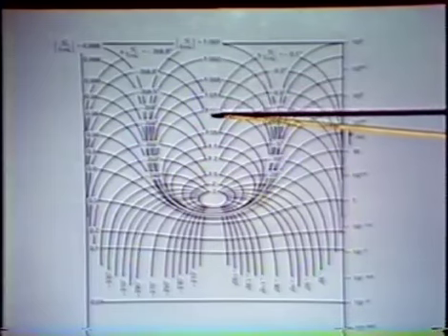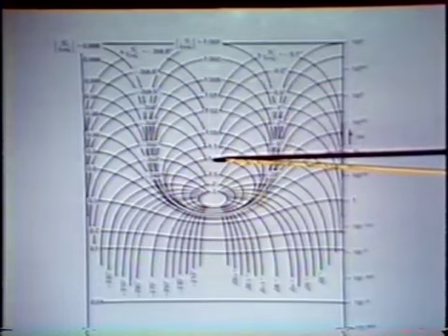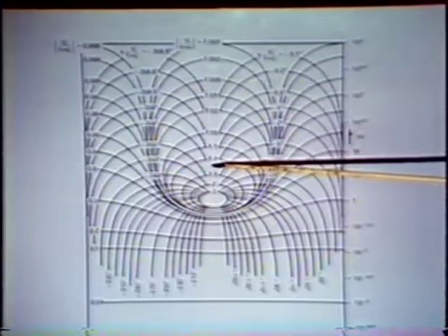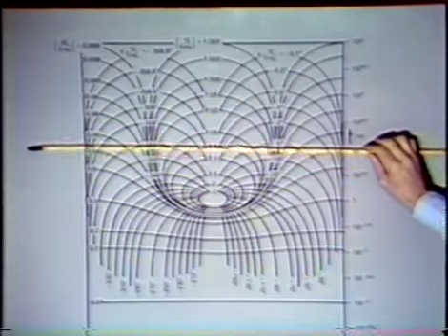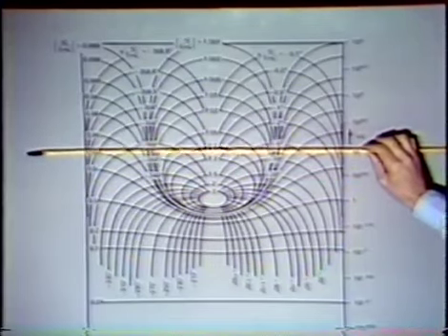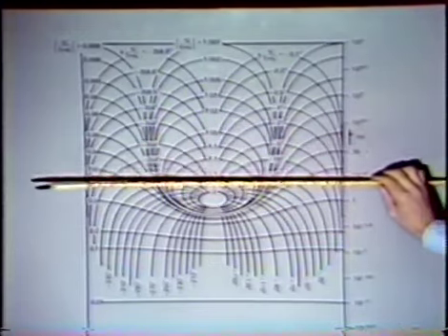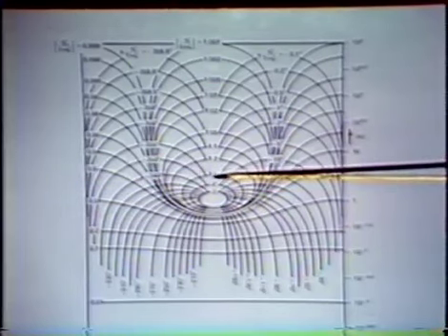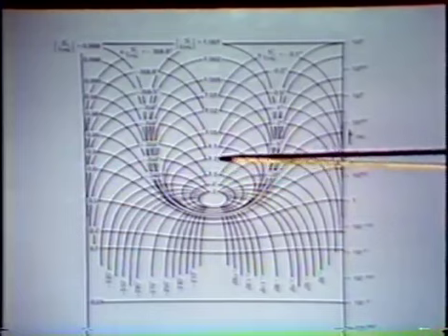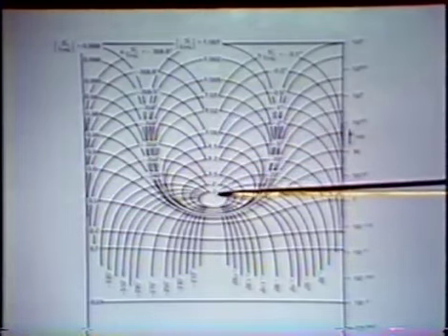And now we're getting closer to G equals 1. Here's G equals 10 and an angle of minus 180 degrees. And we have a magnitude of about 1.1 or 1.2 at that point, about 1.1. And now we're going down to a magnitude of the square root of 10. And we have a magnitude for G over 1 plus G of about 1.5. And here, as we approach the minus 1 point, the magnitude gets larger and larger.